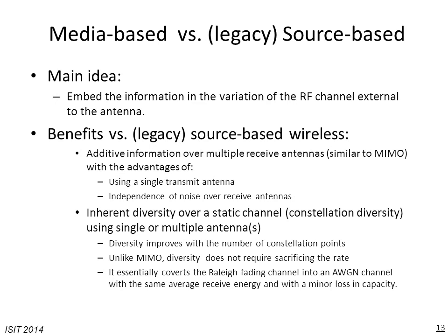So this is one major difference with legacy SIMO systems, in that in a SIMO system the signal received at the destination will always span a single dimension, and the best we can do is to gather the energy through maximum ratio combining at the receiver, which will result in some energy saving but doesn't give a linear increase in the rate as a function of the number of receive antennas.